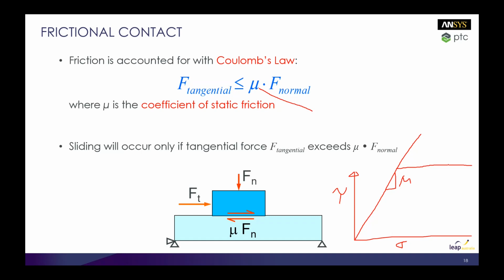So this is essentially a shear stress limit. It's normally 0.6 times the yield stress. You can put that in as a limit, and one of the workshops I'll do will show the effect of that shear stress limit and how it can affect your result.